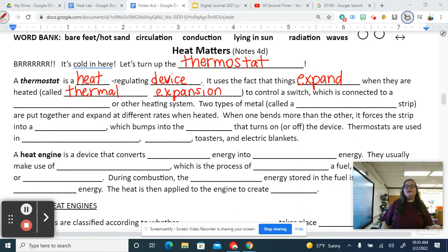The Eiffel Tower can be 4 to 6 inches taller in the summer than it is in the winter due to thermal expansion. All that metal gets hot and it expands. Crazy to think about. When you drive across bridges, very often you'll see a zipper looking thing made out of metal teeth, and it's taking advantage of thermal expansion. It's there because bridges freeze faster because there's no ground underneath them to insulate them. And so those materials expand and contract, expand and contract. And if you didn't allow for that, your road would buckle and fall apart.